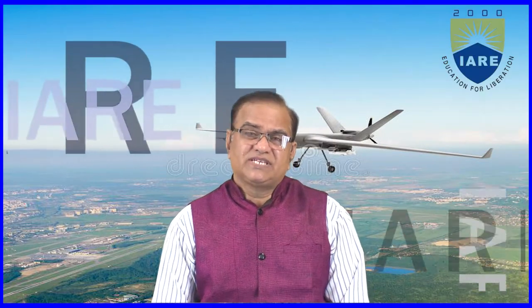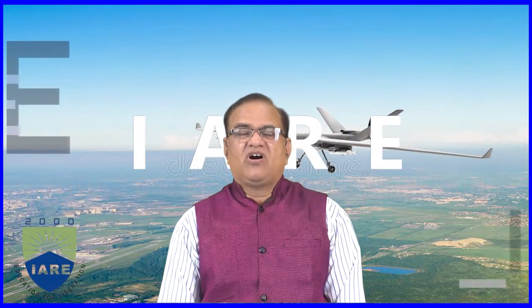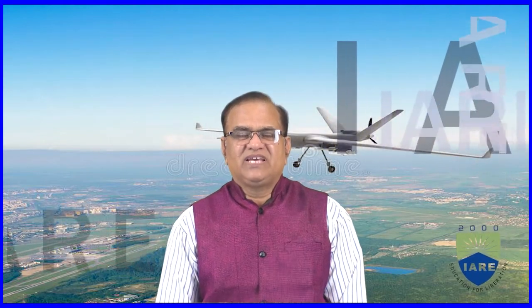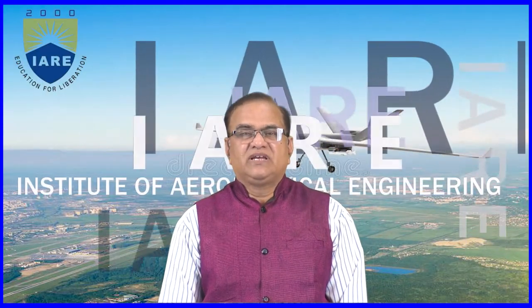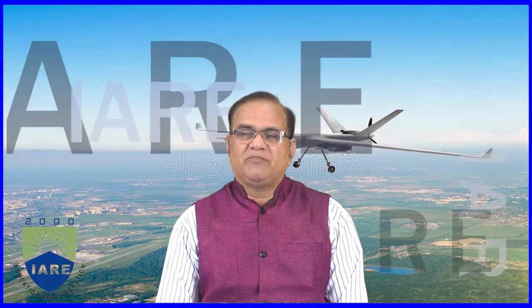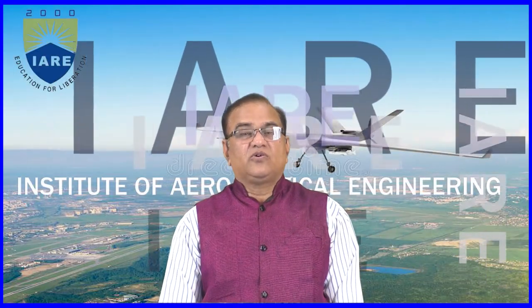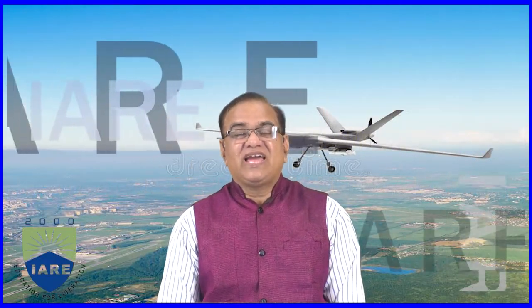So we have done this for the longitudinal case, and we have seen that the horizontal tail plays a very important role in making the aircraft statically longitudinally stable. Because to have static stability, two conditions have to be met for longitudinal static stability. The first condition is Cm0 should be greater than 0. If Cm0 is greater than 0, then we can trim the aircraft at a positive angle of attack.